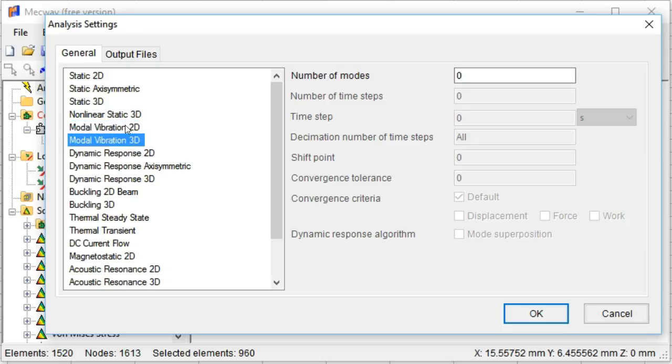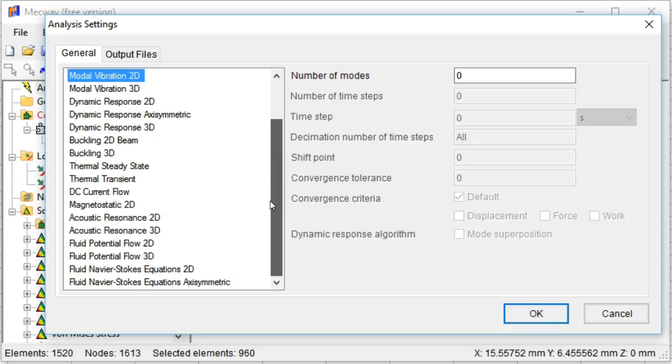It's very interesting to look at the modal vibration to determine where you might want to place your piezoelectric materials and what the resonant frequency is, and that can get you a lot of data. Although it won't get you impedance data or electrical analysis, you'll be pretty well on your way to designing a reasonable transducer using just these analyses. It shows that you have a better understanding if you're able to solve problems with fewer tools, because no matter how much computing power or how capable your programs are, it's only as capable as you are as an engineer. But this can be very sufficient for designing transducers.